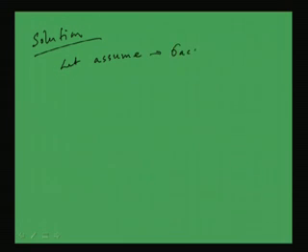So, what will we do? See, if we go for the solution, first we will assume either some radius of gyration, or simply we can assume the sigma AC value. So, let me assume 70 MPa, right.